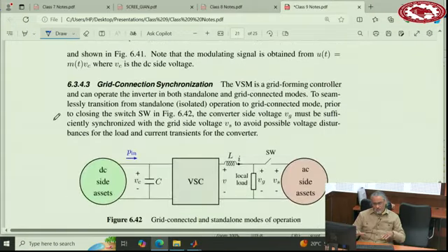And now this VSM, if you look at the whole mechanism, it generates a voltage, regarding the question you asked before. So it's actually a voltage source. It's not even a current-controlled voltage source. So it's a voltage source. It can form a grid, no problem, and it has supportive functions. So if you have a grid and a load, and this switch can open and close, and you have a VSM controller on this converter, it should work. It will not have any problem.